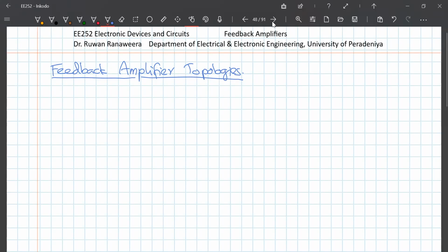You have the whole voltage, you have to get out from it. So it's a series. You cannot connect a network in parallel and subtract a voltage. If you are going to subtract the voltage, it's kind of like when you have a voltage drop somewhere else. So in the series, you have to subtract it in series. So the feedback has to be series if the input type is a voltage.